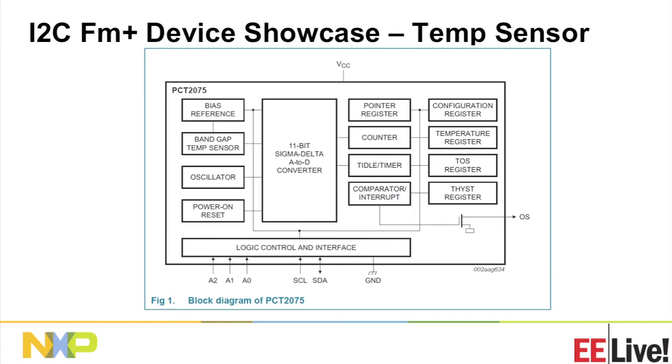Then on this side, we have a number of watchdog devices. We have internal registers that can be used for upper and lower temperature sensing. And there's also a hardware path that if there is an over-temperature condition, which is so severe that it stops your processor from working and the I2C bus is no longer working, we can control some piece of hardware, such as shut down the power supply, turn on the fan, do both, cause an alarm. And then, of course, we have the I2C signals. We have 3 address pins, which means that you can have 8 independent temperature sensors connected on the same bus.